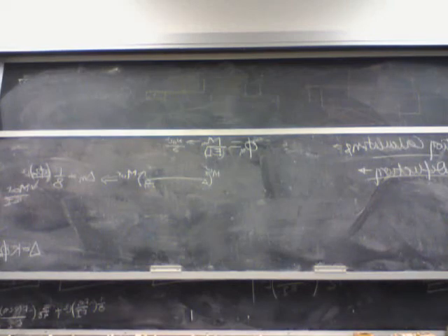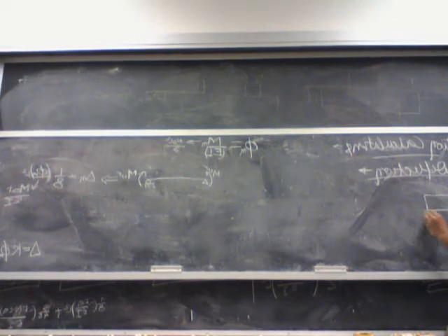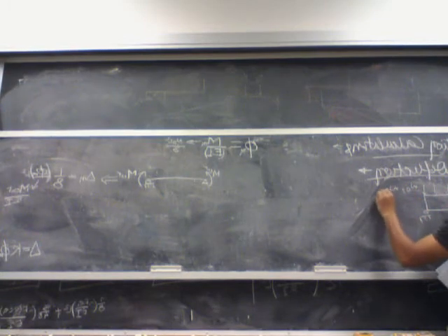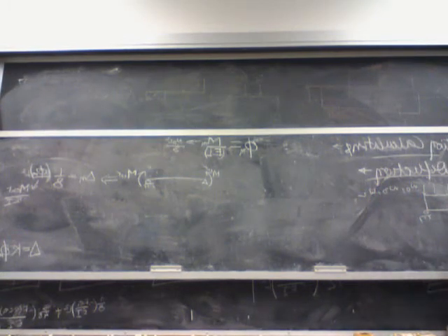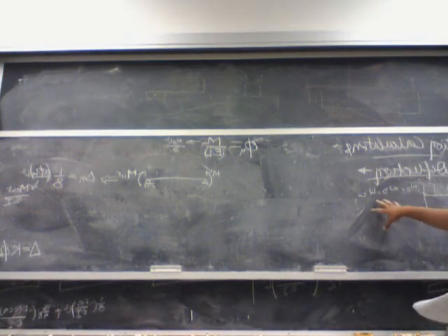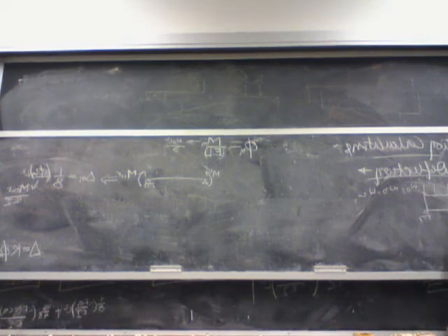So first one is the instantaneous deflection. What I have is a beam. I have some tendon profile on it. I have some loads acting on it, which can be self-weight, dead load, and live load. And I want to find out what is the deflection right after I apply all those loads. So I want to find out what will be the deflection right after all the loads are applied together. So in this case, again, I can use the superposition.